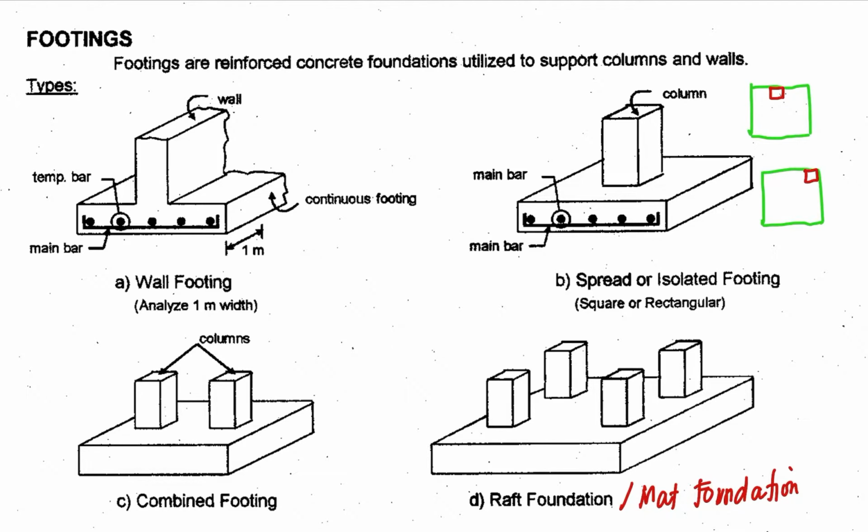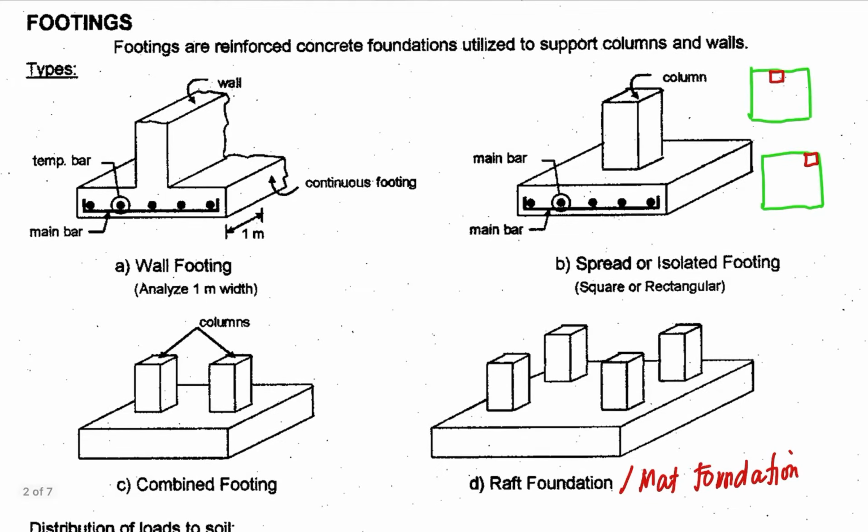Okay, so in some cases when you excavate the area, sometimes you also have this one connecting maybe from column to column or footing to footing, especially when you are using spread footing. Okay, sometimes that connects the footing or column. So for example, this is your footing and another footing and column. You have there the connection. This is the tie beam.